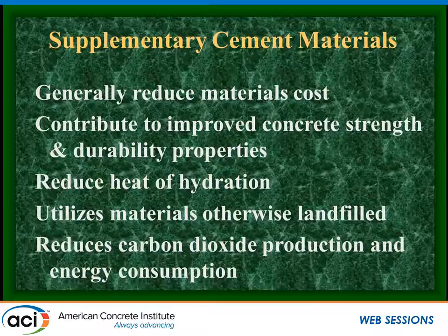We're actually seeing that in most high-performance applications, we're tending to want these waste products in our concrete. Where before, in the beginning, you had to kind of beg an engineer or an owner to let you put this material in their concrete. As we came to understand more the strength and performance properties we were getting from these products, this is something we want to include in our concrete. And this is something that you will almost always see in those high-performance applications, high-strength, high-durability applications.